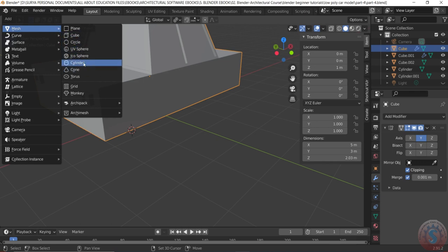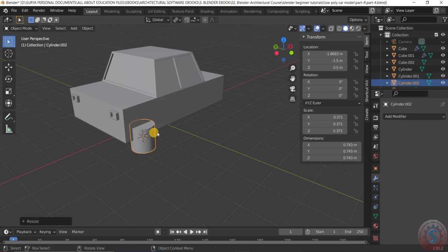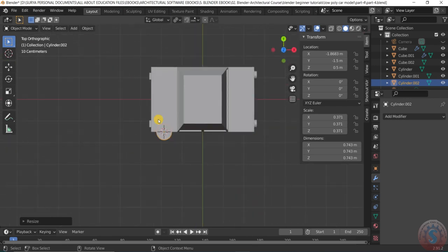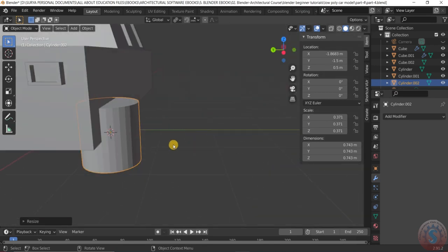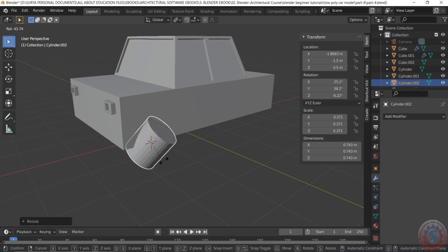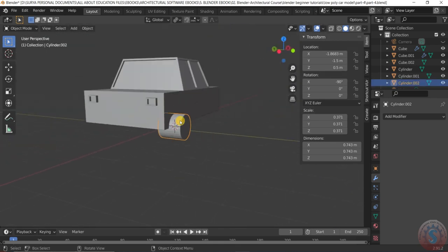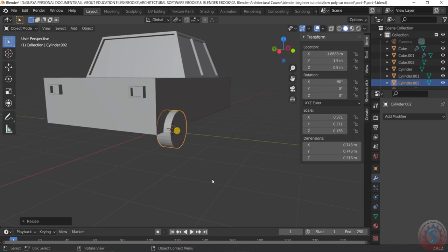It is centered. You can observe here, you can create the cylinder by going to the object mode, Shift A and go into the cylinder and the S key. Somewhat distance, hence again rotate this by pressing on the, you can observe I'm rotating this on the X direction and give the rotation and give the scale to Y option, somewhat decrease this like this.